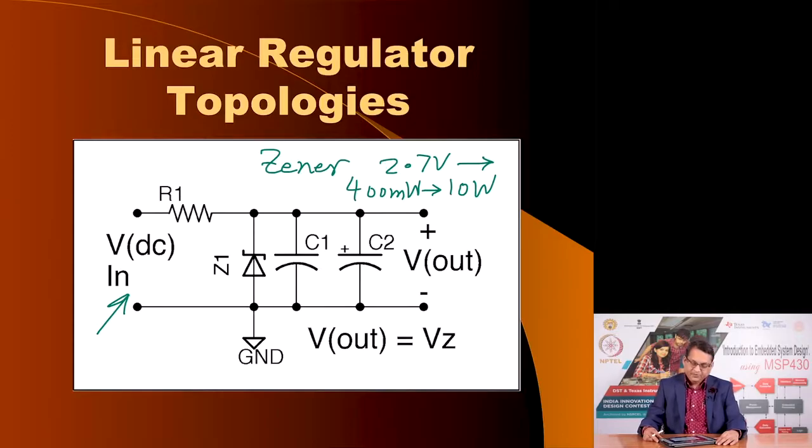and so it could be used to create a power supply system. This is not a very efficient system for various reasons, and it uses several components. One, you need a series limiting resistor, you need the actual Zener diode, and you need 2 capacitors as I mentioned. One of the capacitors, C1, would be a ceramic capacitor and C2 would be an electrolytic capacitor.